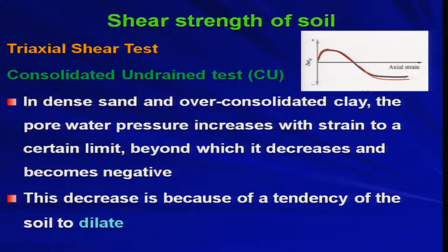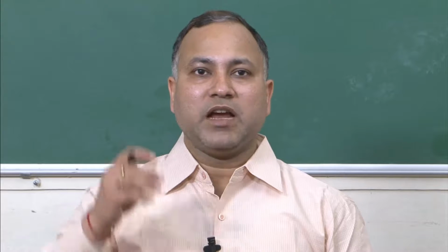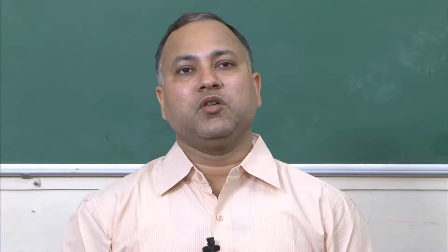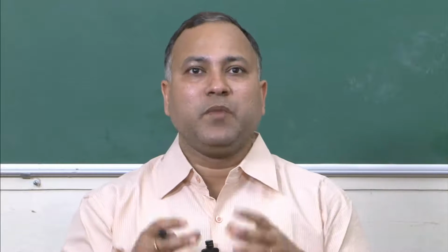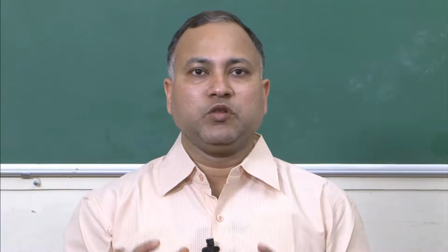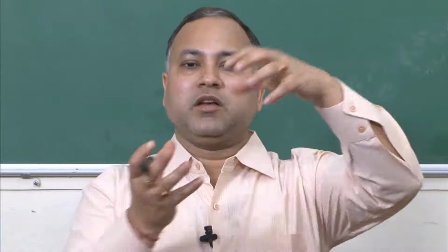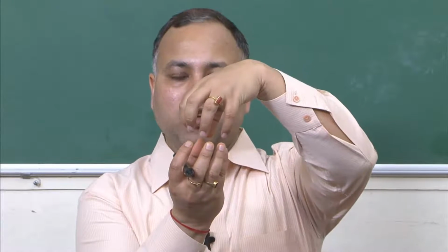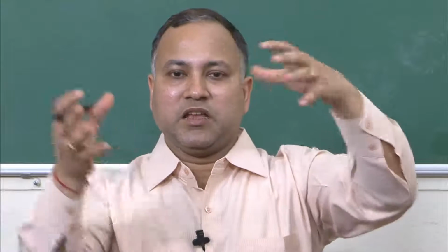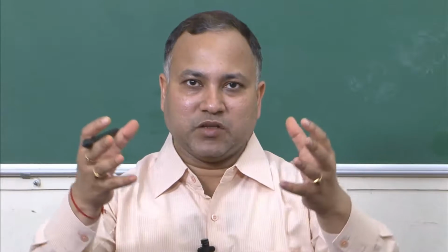So, in case of dense sand or over consolidated clay, if you try to shear it, it will cause some volume expansion, right. So, it will cause some dilation in the soil specimen, due to which you will be getting some suction. That means, when you are increasing the volume due to shear, it will try to attract or accumulate the water inside. So, that means you will be getting some suction in the pore water pressure.